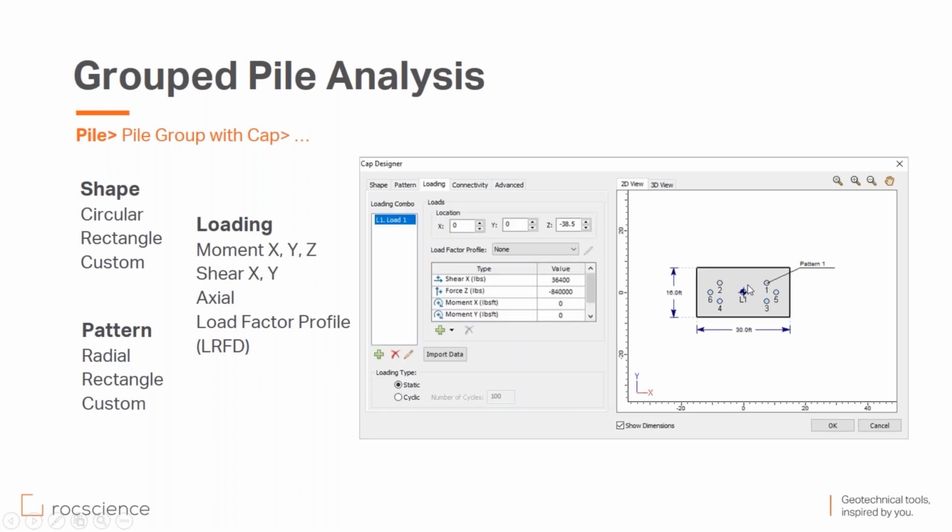And then you add a load. So you can add the load in the middle of your cap, as you can see here, but you can have more than one load anywhere in your pile. And we also have LRFD and cyclic load, same as individual pile analysis.